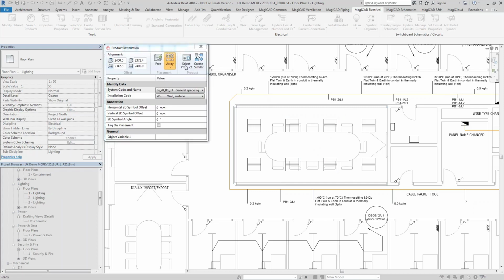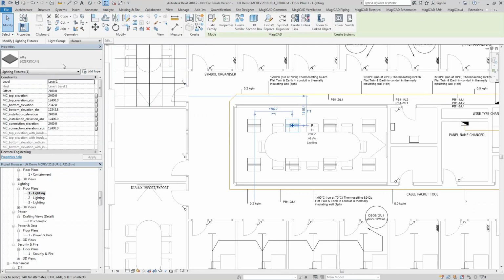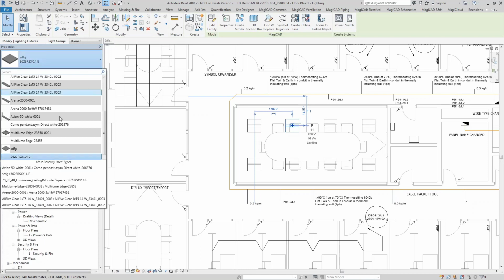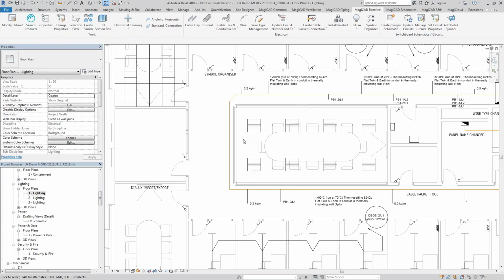And then at that point, it assembles those RFAs and fixes them into my project. So these are now, again, Revit RFAs, just the same as any other. You can change them for another product the same way that you would in Revit out of the box. Additionally to that, we also have a find and replace tool, but again, I'm not going to go into the details of that, but we have many non-discipline specific tools which you can use alongside the electrical module to help provide the look that you're after.